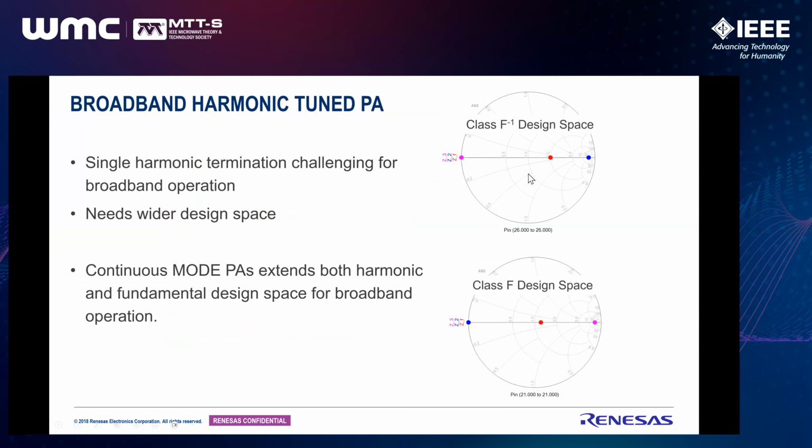So more examples here. To quantify that, we can literally model the input nonlinearity. Let's say when it is linear, like one sinusoidal, we can consider V1 cos theta. When we are considering up to second harmonic source, we introduce a second harmonic input voltage component.